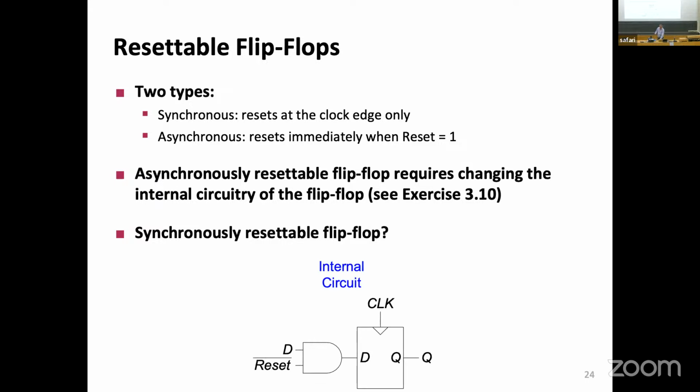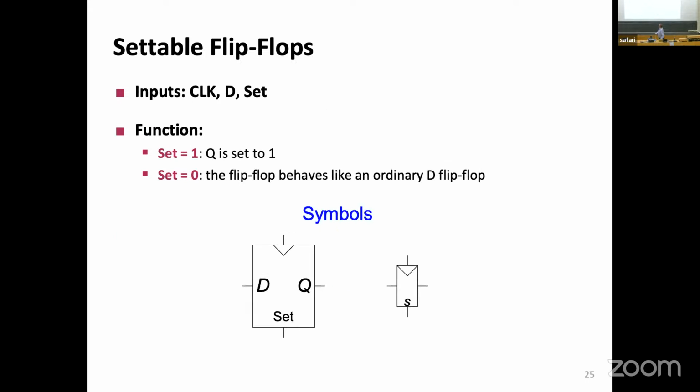Now, if you have resettable, you also have settable flip-flops. The idea is the same. You may want to have the initial value of the flip-flop to be 1. So the signal in this case is called set signal, not reset signal.